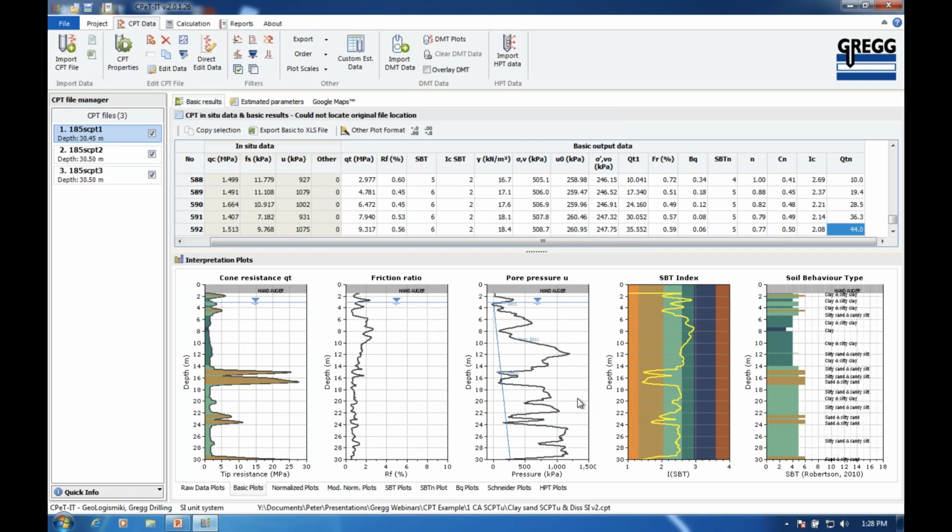Often the key is the cone is going to interpret the data based on what the effective stresses in the ground are. Now, if they're suctions, you don't actually know what they are, but the cone is going to respond to the strength and stiffness of the soil at that effective stress. So if that's what the suction is going to be in the future, then you maybe don't care that you don't know what it is.